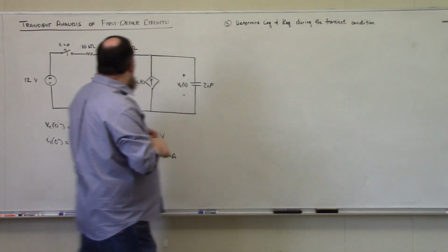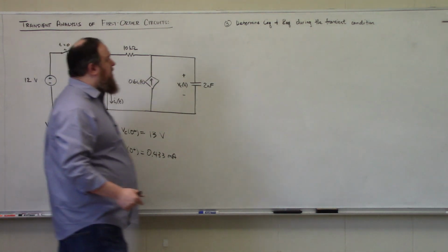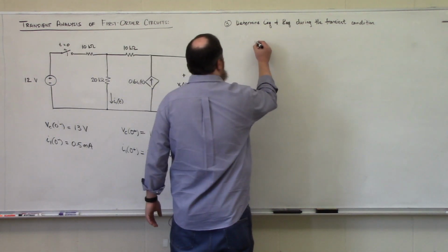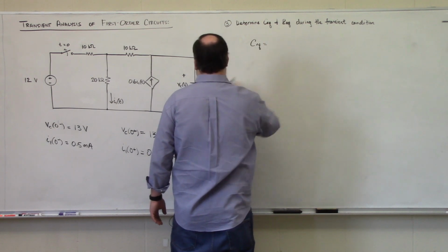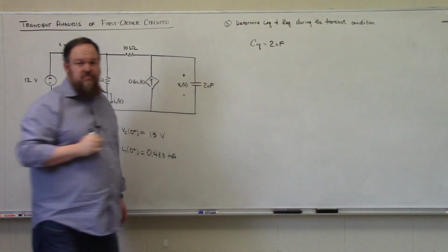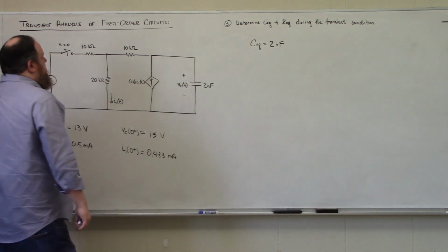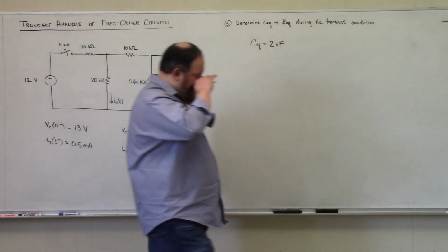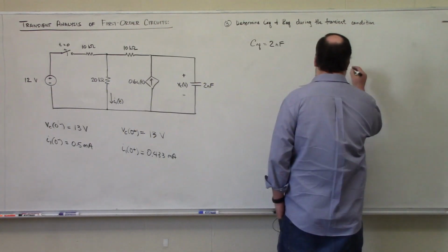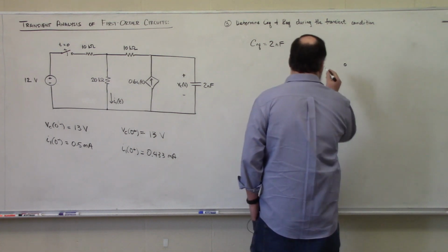Alrighty, so again, there's only a single capacitor in our entire circuit, so I'm going to go out on an adventuresome limb here and assume that CEQ is equal to 2 nanofarads because I literally don't comprehend how it could be anything else. To determine REQ, we are going to have to find the Thevenin equivalent resistance from the perspective of the capacitor.